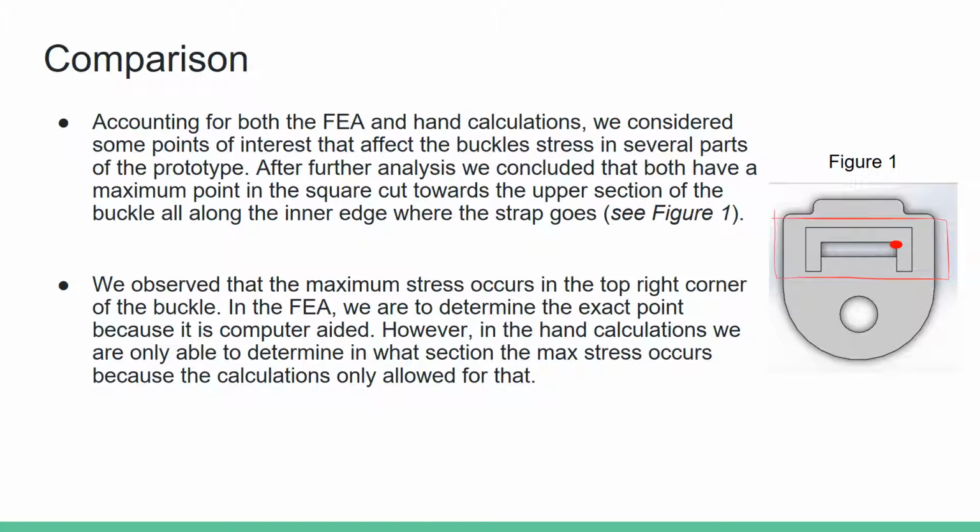We also observed that the FEA determines the exact point of maximum stress because it is computer aided. However, in our hand calculations, we were only able to determine in what section the max stress will actually occur, because the calculations only allowed for that.